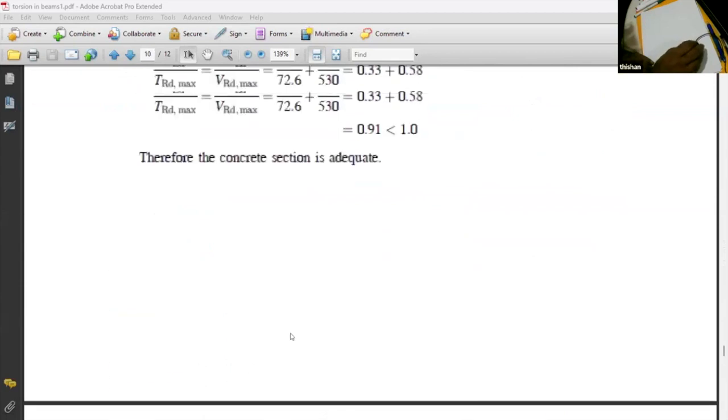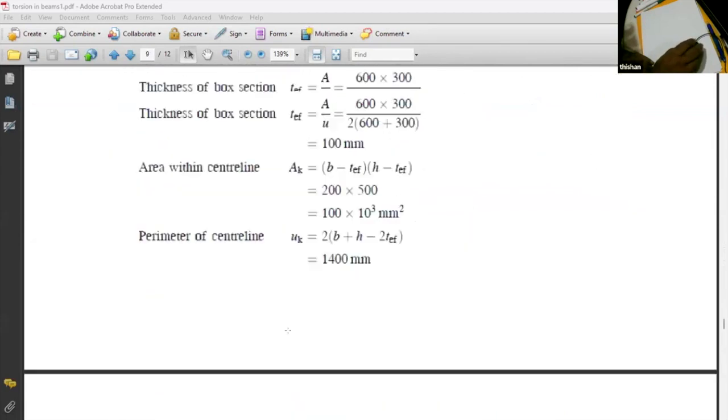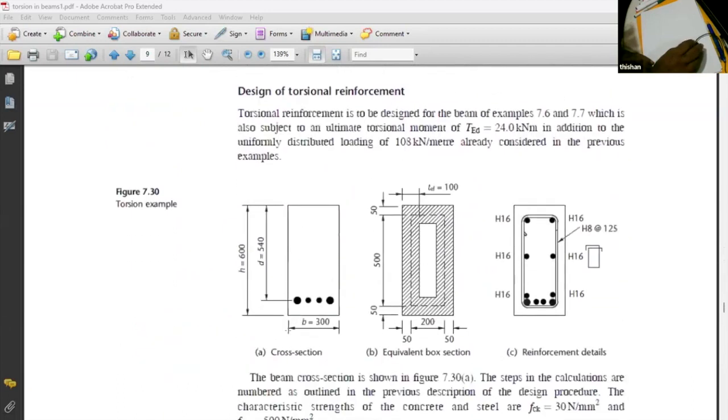Because can you remember last time? Bandukar, I hope you can remember. We said when you are designing a rectangular section, we design it as a hollow section and provide the reinforcement requirement, right? Yes, sir. Also, if you look at the shape of the link, can you remember this shape I have drawn and shown you? Yes, sir. We did that. This is the torsional link, right? So any section subject to torsion, we need torsional link.